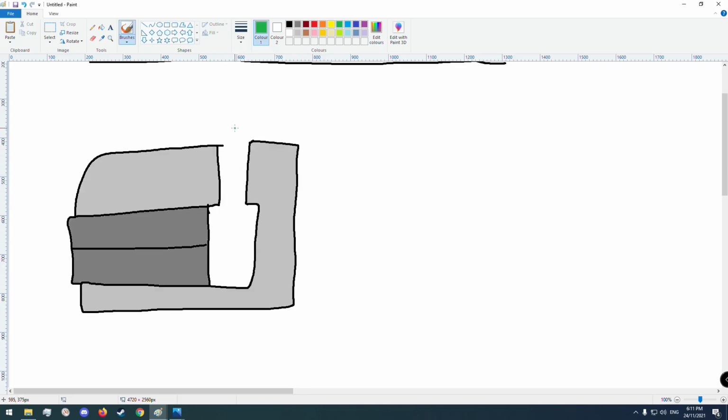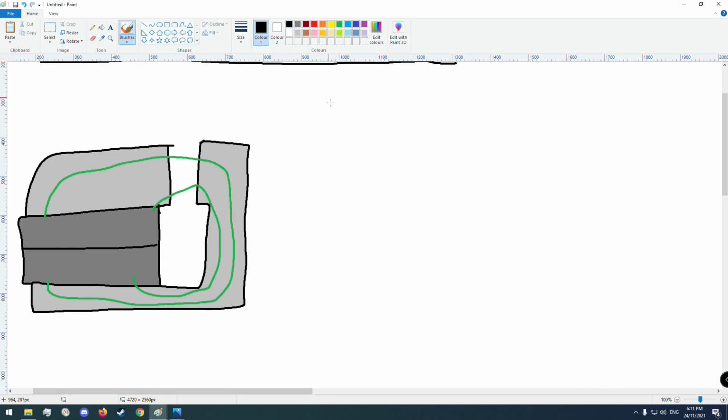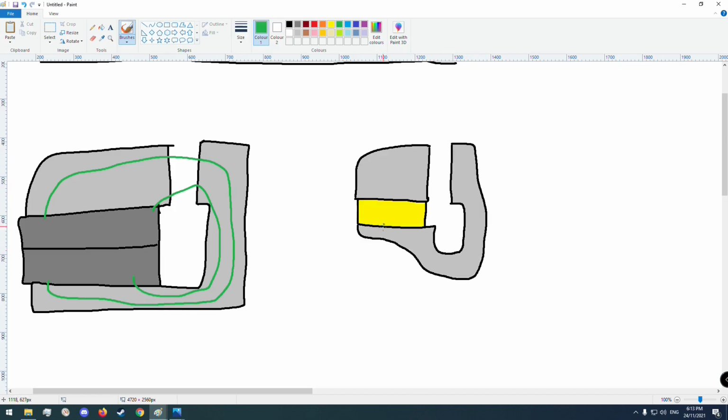So yeah, this is just a really rough sketch of the cross section of a motor. You can see right here the flux would come up and around here, and in a neodymium motor, because it's so much stronger, what you can do is have a setup just like this, where you have a lot less neodymium magnet but get the same strength through roughly the same area. So this makes speakers that are made of neodymium a lot lighter.